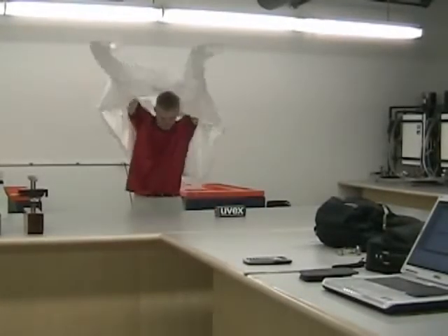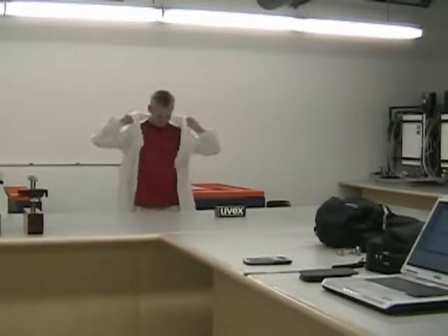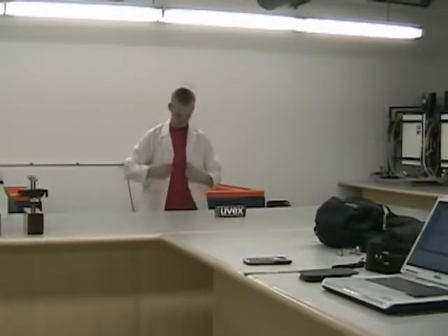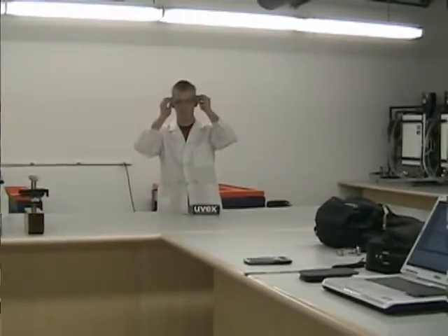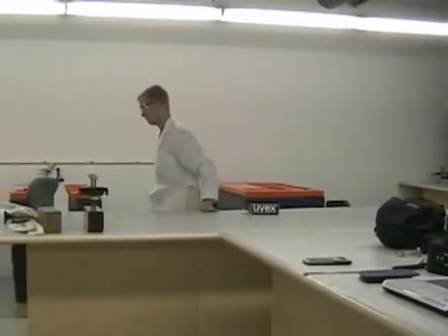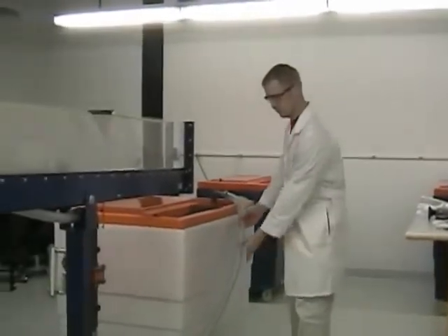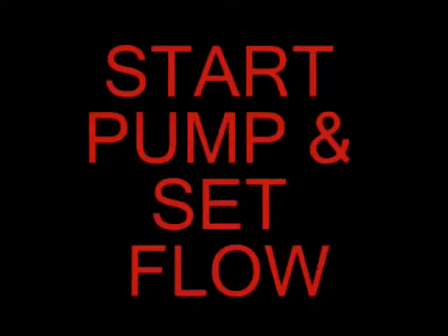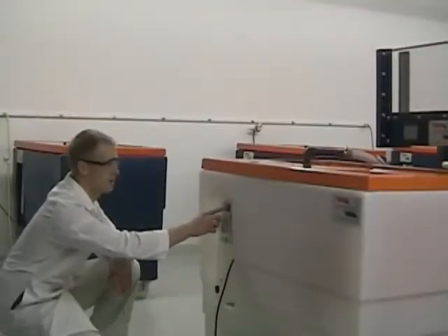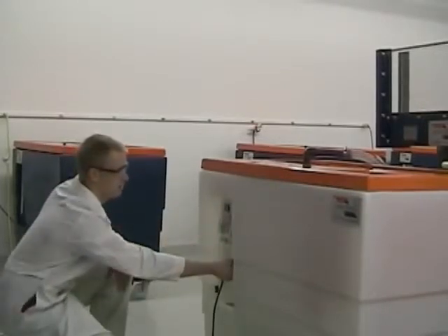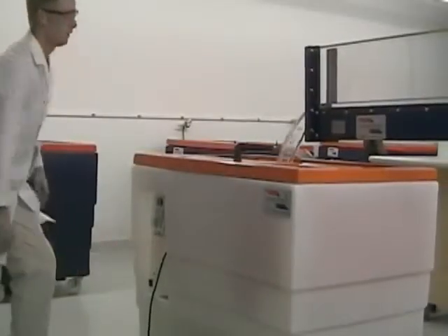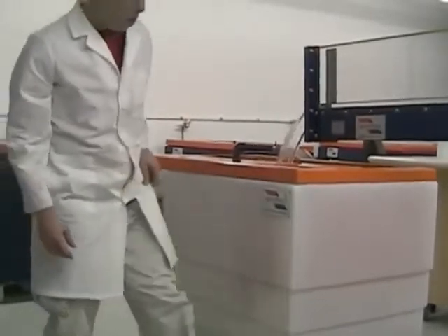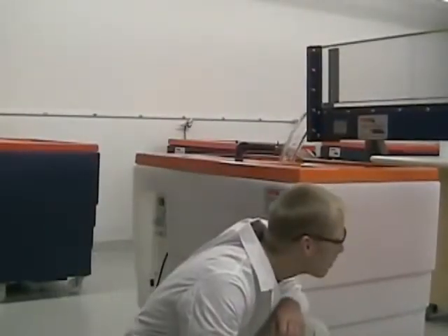Protective clothing is a good idea, but not required for this exercise. Before we start the flume, the hoses must be checked for loose connections to prevent leakage. You can now start the pump and set the flow rate. The flow rate may be roughly adjusted to the desired flow rate by using the flow rate gauge below the end of the flume.